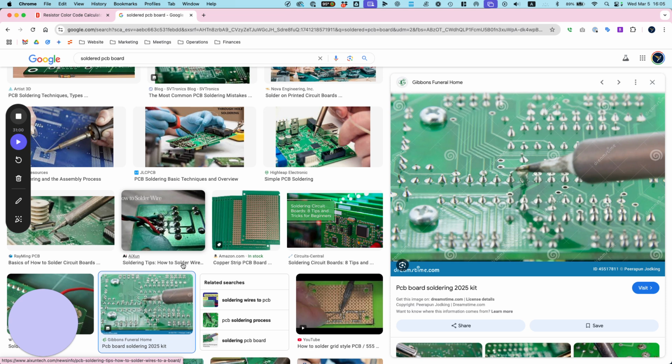Or you have this type, which is orange on one side and green on the other. If you look at the green on the back side, they are actually connected by the letters. Do you see A through W? Okay, those are your columns. Those columns are all connected underneath. So this is like a one-layer PCB board. There's a channel underneath. Each of them are electrically connected. So if you touch the multimeter on anything in the same column, it will beep in continuity mode, because they're all connected. Meaning, you don't need to bridge things if you connect things on the same column.